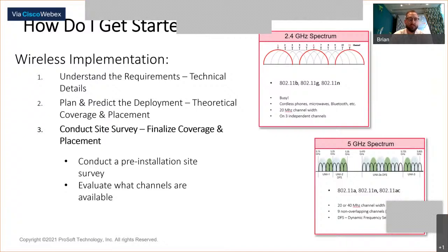So it's important when choosing a channel to choose one that's free from other networks. That's critical. To do this, you can conduct a site survey. There's several third-party tools that are available, or you can simply use our radio and RLX2 to sniff the spectrum and evaluate a list of channels that are used, what devices are on them, and the signal strength of those systems. That's all built into our product, so it's easy to do.